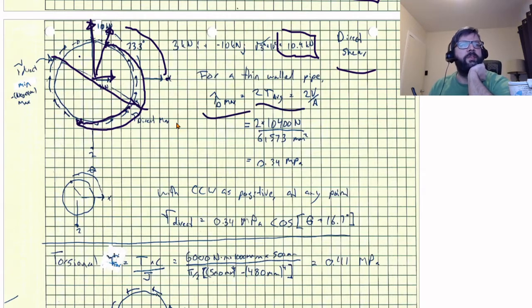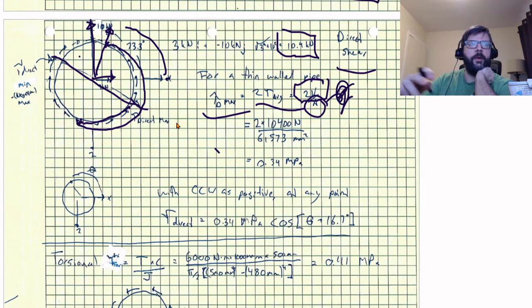And the magnitude of that maximum ends up being 2 times the average shear, so 2 times the shear load divided by the area. You could look that up if you want, or you could derive it just by calculating your shear flow. Either way works. Obviously, looking it up is usually going to be a bit quicker.